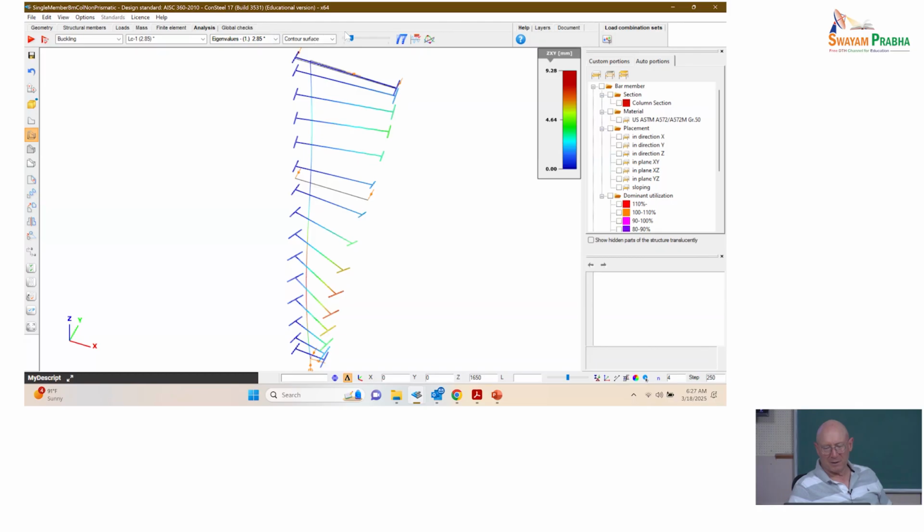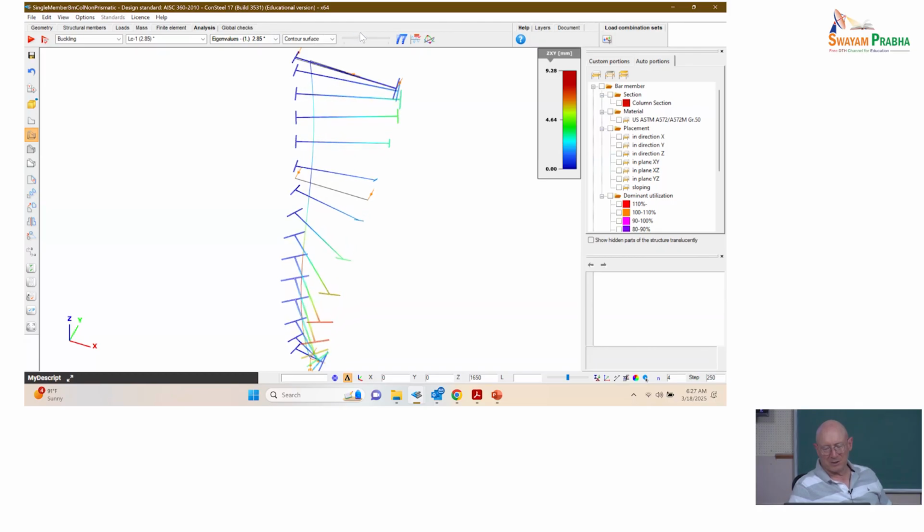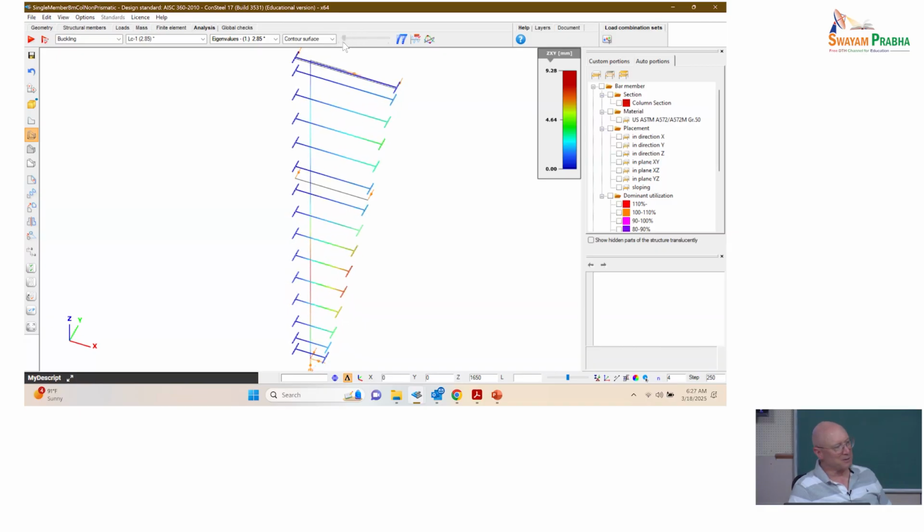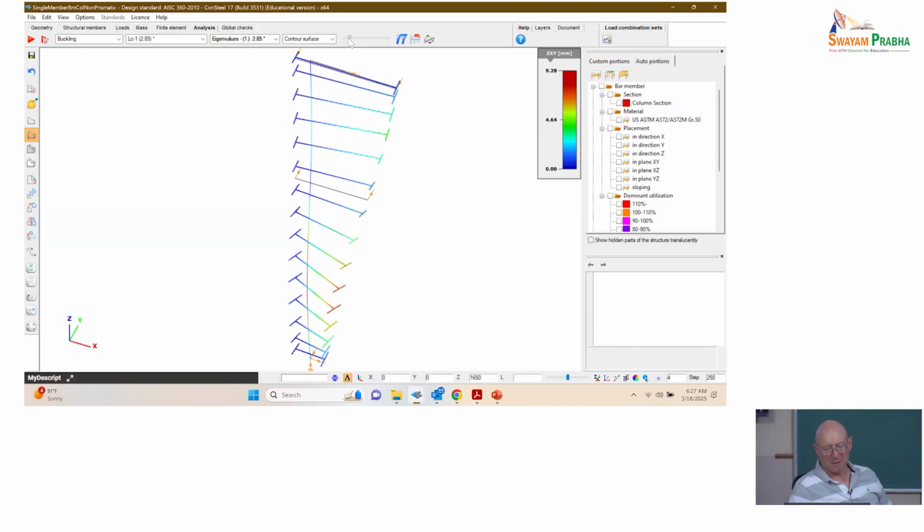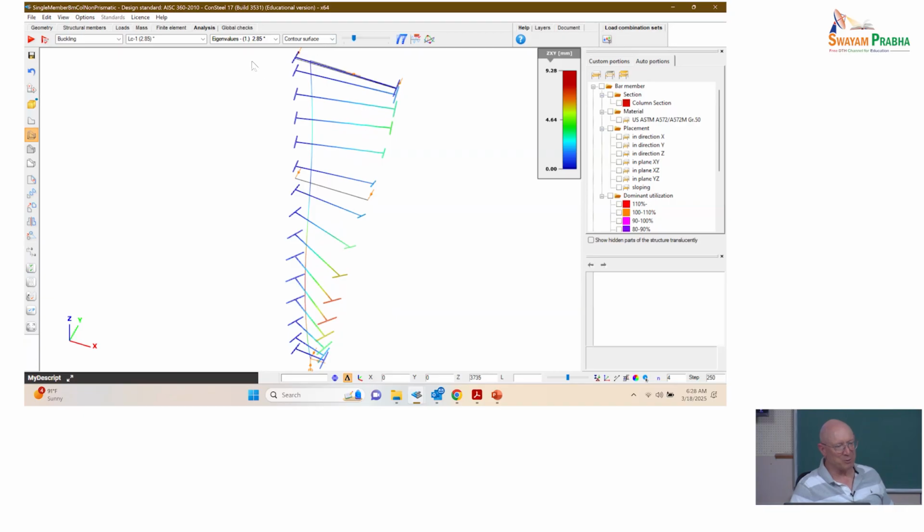You can see that we're getting still fairly significant action in the top unbraced length. That's where the moment is highest. And remember, these metal building frames, they're typically just glorified beams. They're dominant flexure. And what are we doing with the non-prismatic geometry? We're basically following the moment envelope and getting a more efficient design by following the moment envelope, right? But they've got some significant axial compression in them that we can't ignore. So we've got to deal with that.